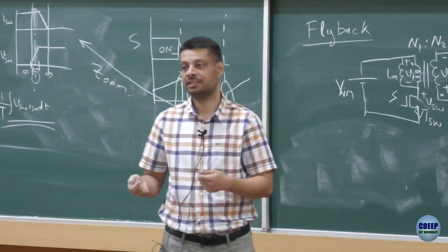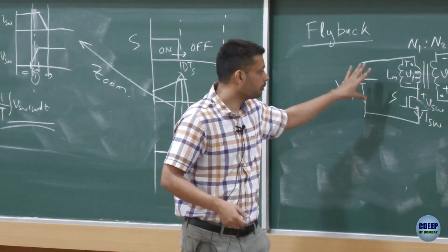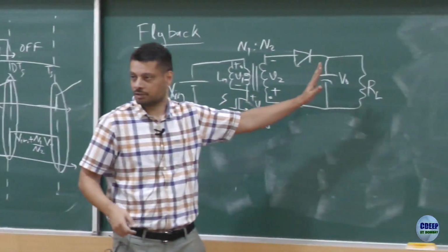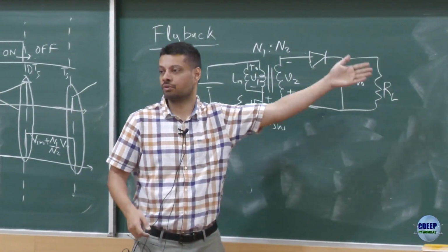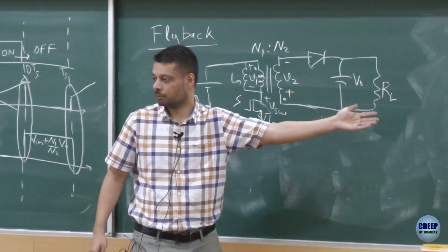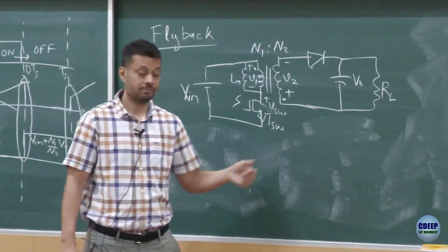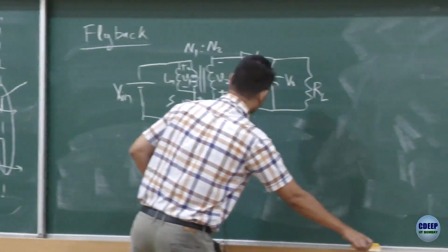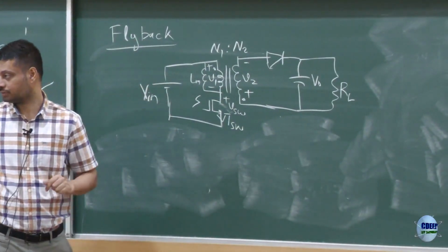Now how do you achieve those? One option is you use a flyback circuit, right? From 400 volt you get 5 volt. Now you can do a 5 to 12 boost to get 12 volt, you can do a buck to get 3.3. The other way, and what is really good about the flyback circuit, is that just one circuit can actually give you multiple outputs.